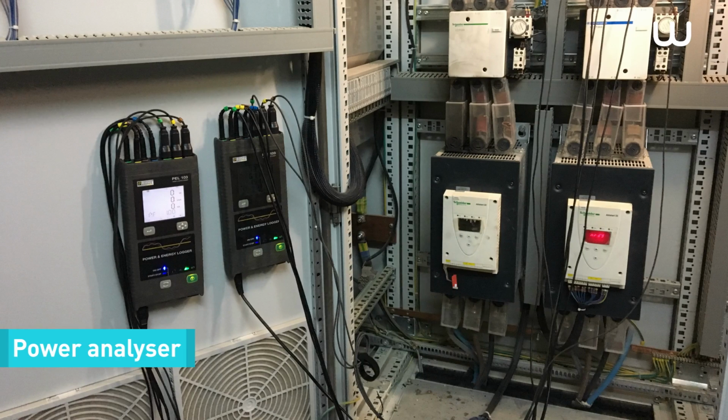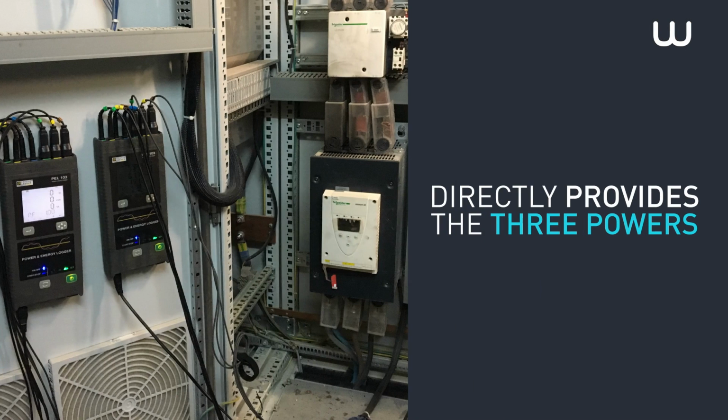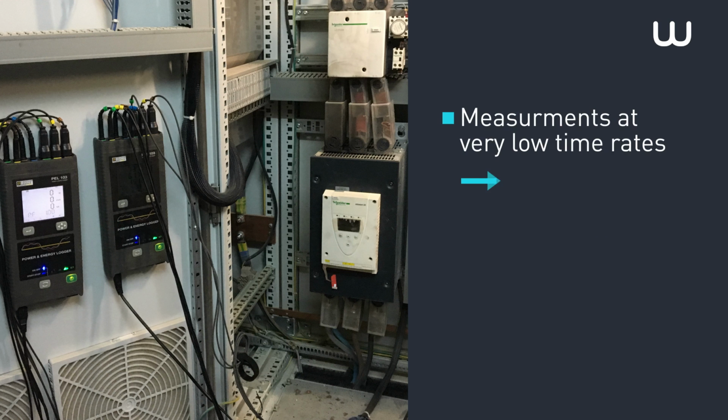The power analyzer is a more sophisticated tool, enabling more accurate electrical measurements to be taken in parallel and for all phases. It directly provides the 3-phase power previously cited, so there's no need to calculate these. Thanks to its ability to record information, the power analyzer collects measurements at very low time rates of around a millisecond to a second, enabling electricity supply harmonics to be measured.